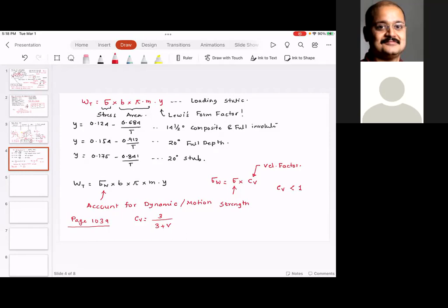Depending upon how accurate the tool is, depending upon how precise the tolerances are on the tool, there are different types of gears, and that's why there are different grades of gear, and that's why the same module, same PCD gear would cost differently for different applications.